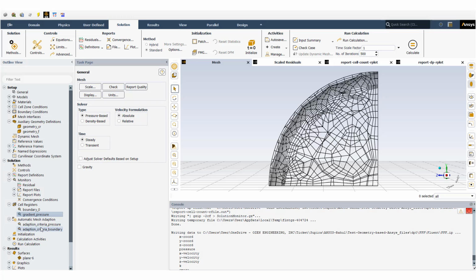Remember that if we really have a geometry that has many sharp corners and is complicated everywhere, and we want to manually refine the mesh, then the number of mesh cells increases exponentially. And it is really hard to partition different parts of the domain so that they get a good refinement for the mesh. It takes time, but instead we can use this geometry based mesh adaptation, specifically using the background mesh from the surface mesh of the same geometry, and use it toward the geometry based mesh adaptation that correctly reconstructs the curved boundaries of the geometry.